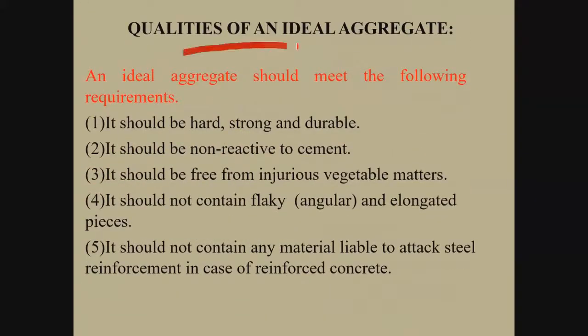Now, what should be the qualities of an ideal aggregate? An ideal aggregate should meet the following requirements. Number one, it should be hard, strong, and durable, so that the resultant concrete will also be hard, strong, and durable. If the aggregates are not hard, strong, and durable, the resultant concrete will not be hard, strong, and durable. Then it should be non-reactive to cement.